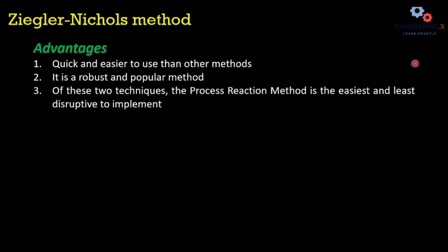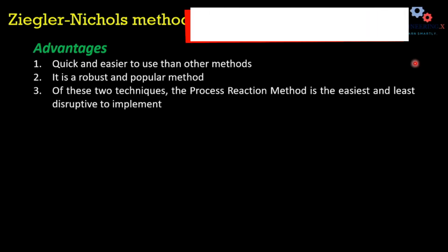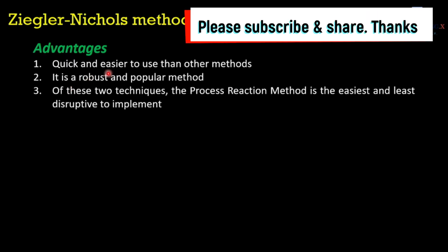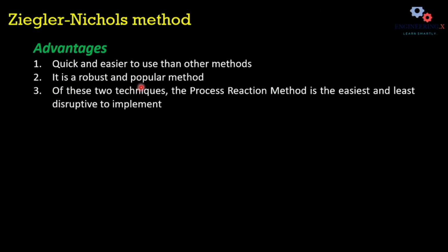There are some advantages of this method as well as some disadvantages. The first advantage is it's quick, easier, and not a complex method. It is a robust and very popular method, and of these techniques, the process reaction method is the easiest and the least disruptive to implement.